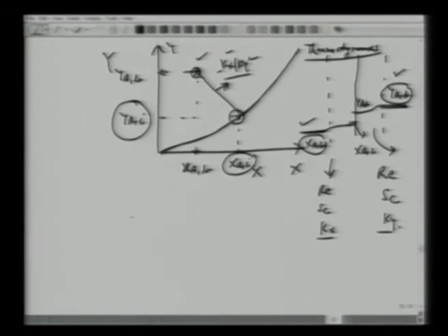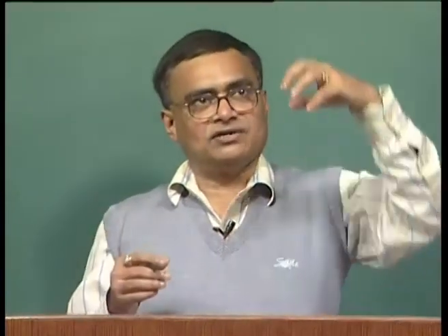And now the problem comes here: what are these interfacial concentrations and how can we measure them? It's very difficult. If you have a flowing system, with a gas phase, say sulfur dioxide, going from the bottom to the top and water trickling from the top to the bottom, and we have the interface, right? If you're asked to measure the concentrations, all we can do is take samples of gas from the bulk or samples of liquid from the bulk.